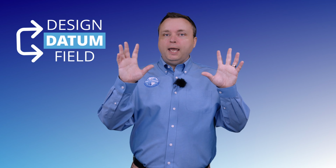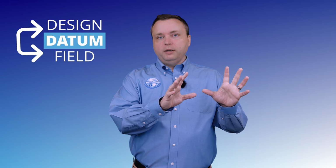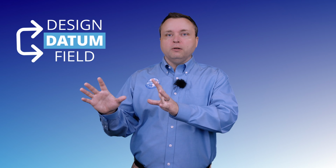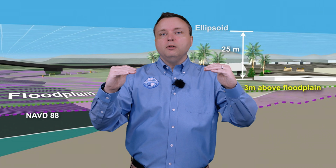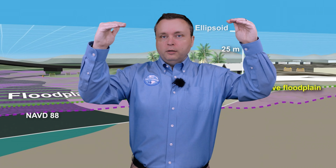But if a design professional chooses one datum and a survey field professional chooses another datum, then we're going to be in real trouble because we think that the condo is built plus 5 feet, which is approved in the county, in the city, for flood hazards. But if you choose the wrong datum, you could build it too low and not meet county standards, or you could build it much too high and you're using millions of dollars in fill dirt when you didn't have to.